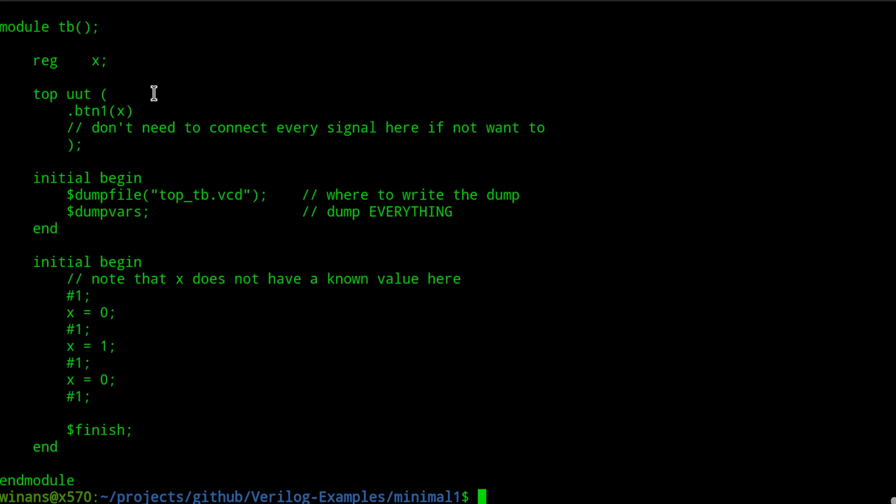Okay? Now, the outputs I don't care about with regard to testing in this simple test bench. I'm not going to look at the output and say, gee, I hope it's set to this value right now to verify that it's correct. All I'm going to do is exercise the inputs with the sole purpose of plotting it on my screen so I can look at it with my eyes. Later on, we'll write a test bench that connects outputs up into the top module and sends data in there, and then reads the output from that module. Then down here in this part of the code, we'll say, put this value in and make sure it says this other value out. And we can automate the testing, all right? It's more complicated. This is ugly enough as it is. We're just trying to light up one little LED here for now, okay? So let's keep it as simple as I can conceive it to be, right?